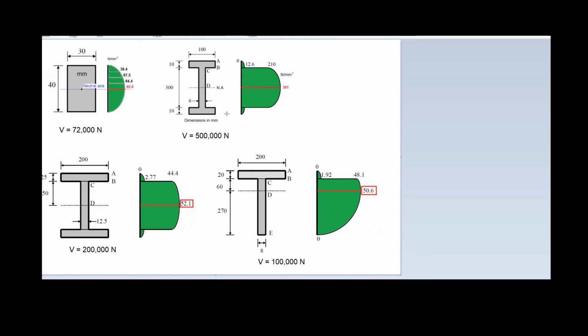When you have an I section or you have a channel or a C section, you can do for the C section the same calculation and get the diagram, and you will see that the diagram will be the same shape. You will have this parabolic distribution in every part and it will be symmetric because the cross section is symmetric. It's double symmetric, actually. It's symmetric regarding the vertical axis and symmetric regarding the horizontal axis, which is the neutral axis. And the only difference you see with respect to the T section is that for half of the section from the neutral axis on top,